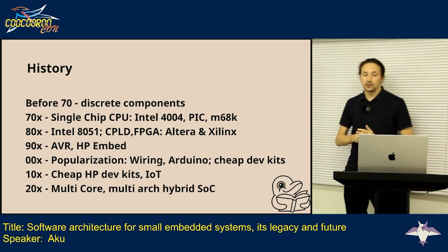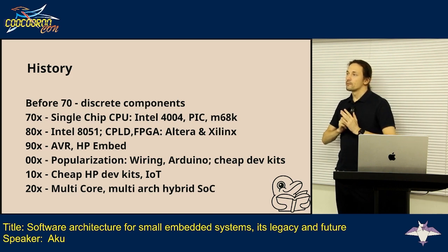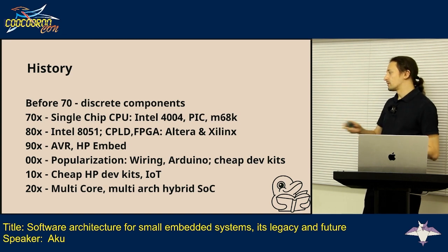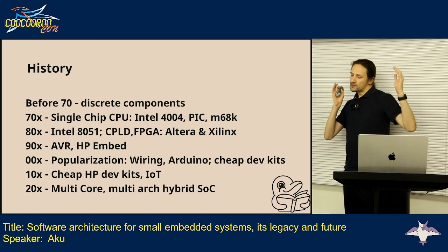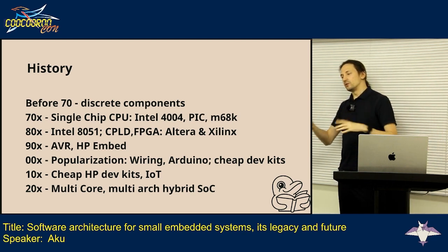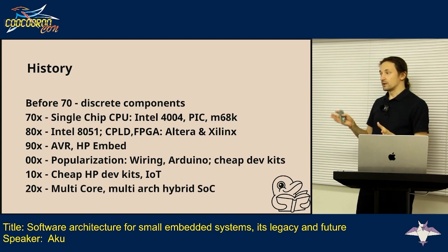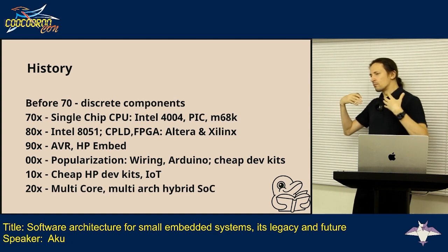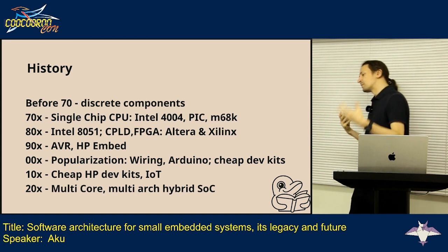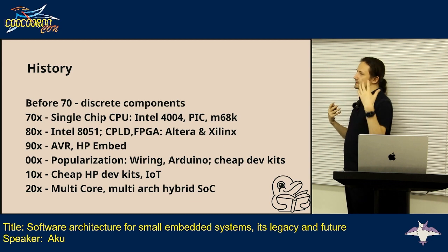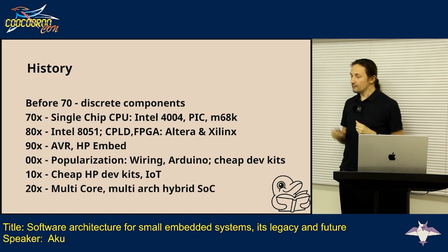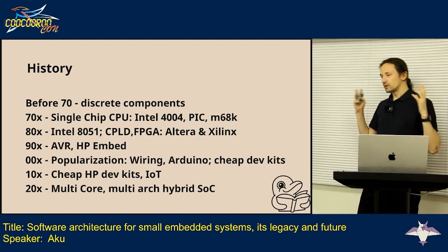And now we see something a little bit different. We know that we have an area with hard real-time and an area with non-real-time systems, and usually, let's say you're designing some kind of device where you want to have both of them. Let's say you want Linux with a user interface, and then you want hard real-time to control something that doesn't like it when you're missing deadlines. And now we have all of them in one package.